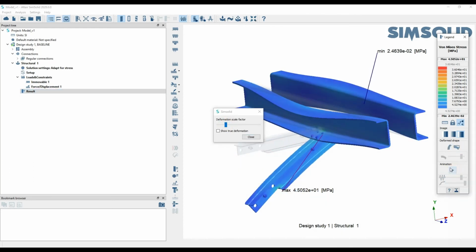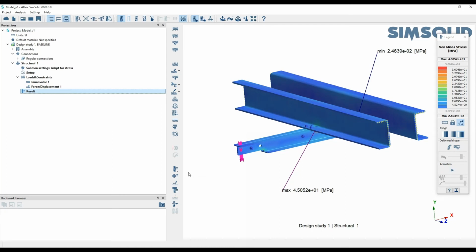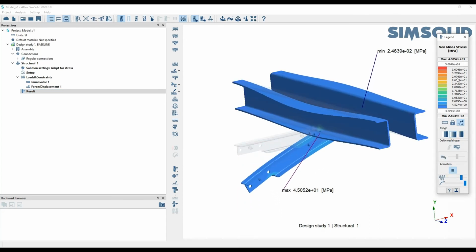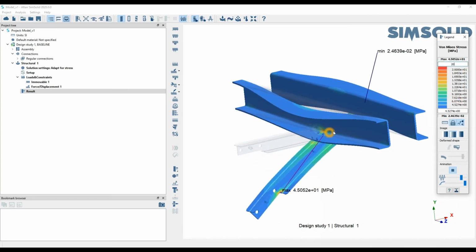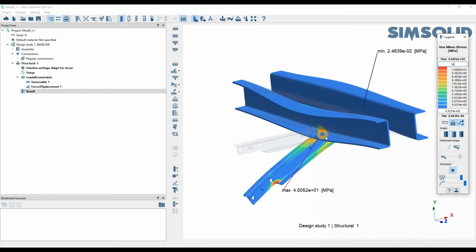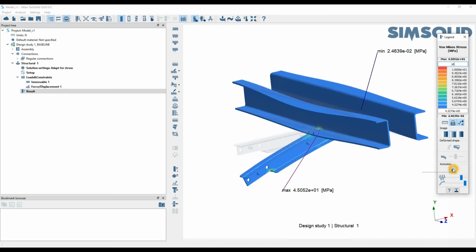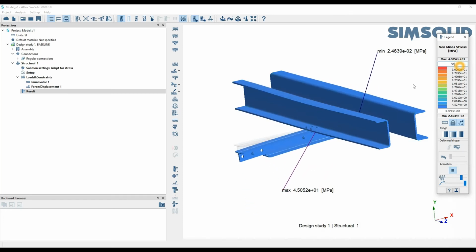Now by default you always get the same set of results. So you'll always get displacements, stresses and strains, and you can look at your stress contour plots in the form of a factor of safety as well. And obviously that's just done with respect to your material's yield value. You can also change your legend at the top, so your maximum values, if I specify that 20, you can see there's a lot more areas which will exceed the 20 mark, and if we do it to 10 as well, then you can see it done again. But if I just leave that back to 30.